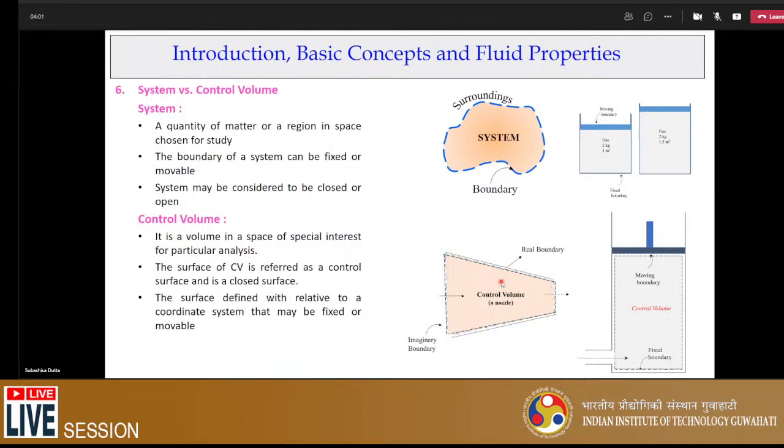For more detail on control volumes, how to sketch a control volume strategically is similar to the free body diagrams you draw in engineering mechanics. So in fluid mechanics, if you want to be an expert and solve different types of fluid problems, you should try to sketch an appropriate control volume. Then you apply the basic conservation equations: mass conservation, linear momentum, angular momentum, and energy conservation, using Reynolds transport theorems.